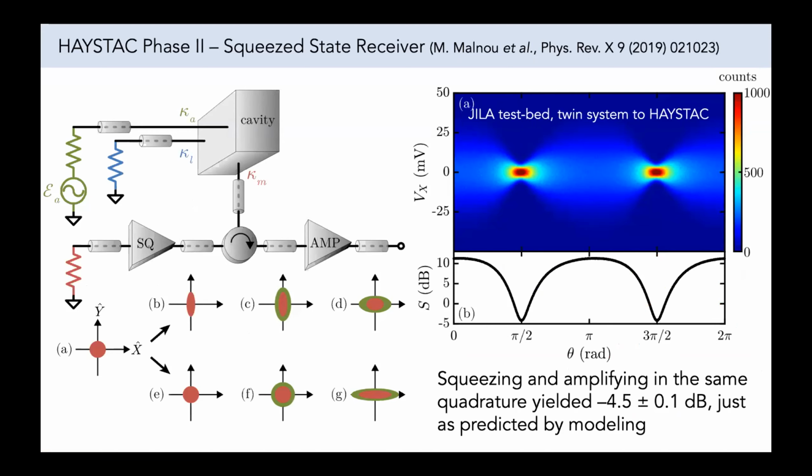By the fluctuation dissipation theorem, you have noise associated with the losses in the cavity. Of course, the black body photons can be reduced down to essentially negligible levels. You have intrinsic losses and noise by the electronic components themselves.